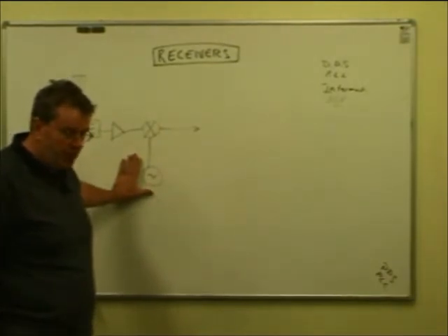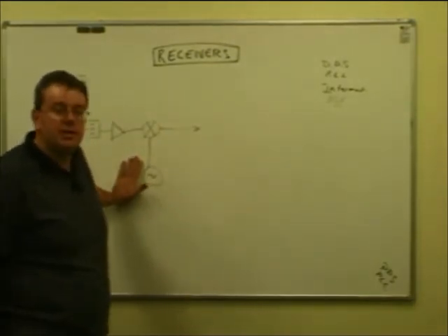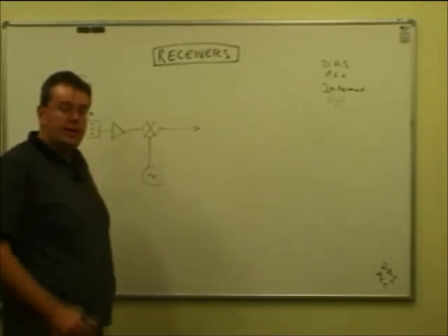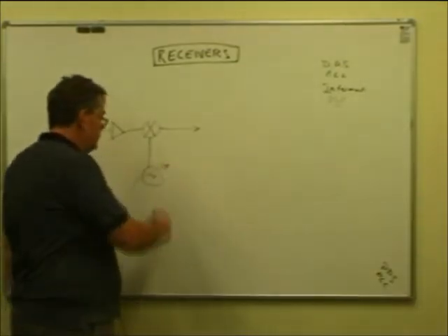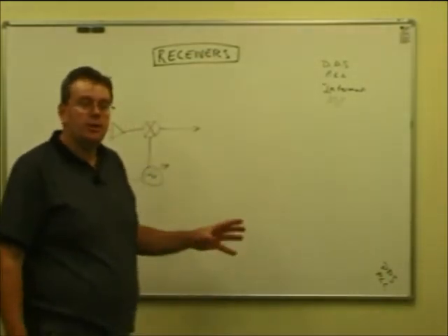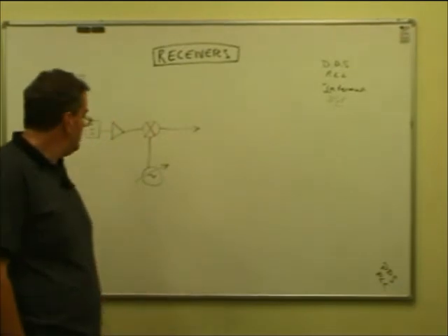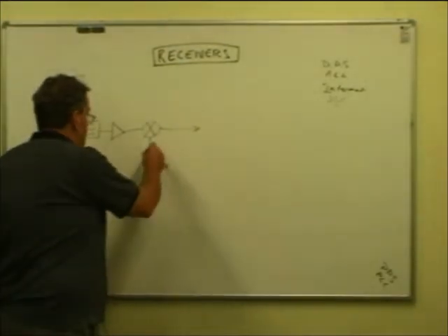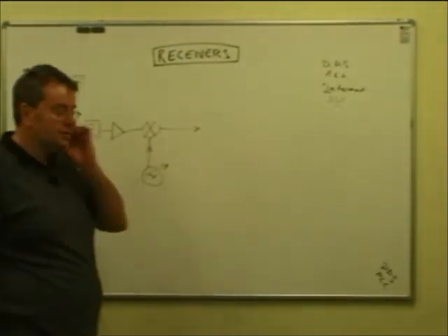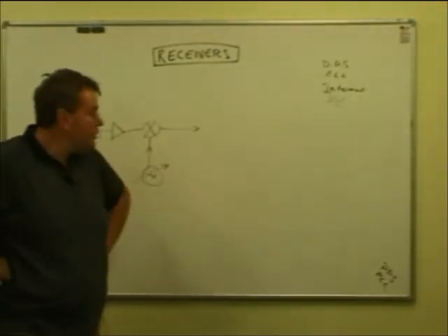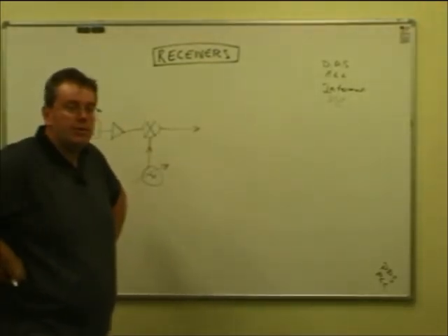Now, up until the 1970s, and currently with homemade gear, that local oscillator is an adjustable thing, an inductor and capacitor combination, a tuned circuit built into an amplifier which is made to oscillate according to the setting of the tuned circuit. And that produces the signal that's injected into the mixer. And we're talking radios like the FT101 and TS520 that you might come across on eBay or Trade Me.